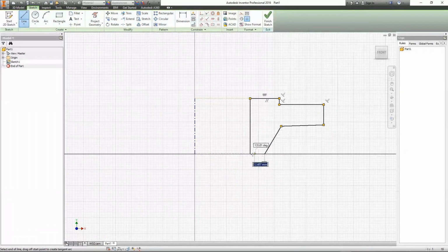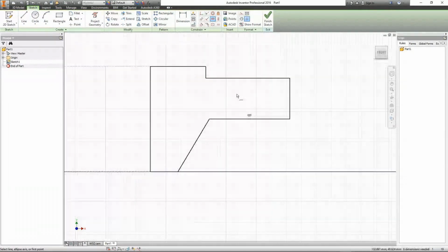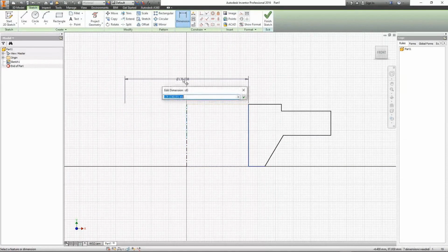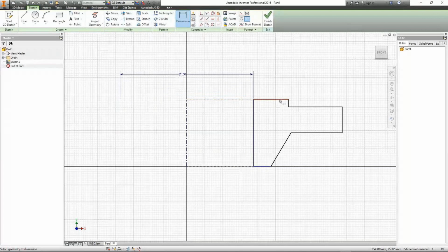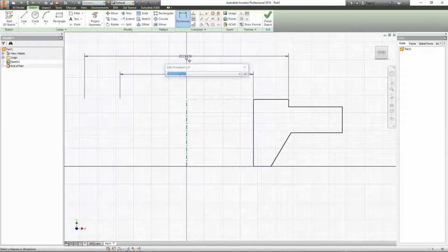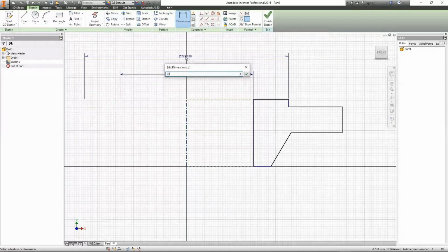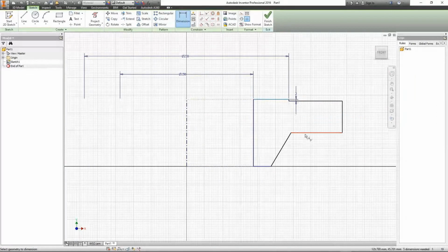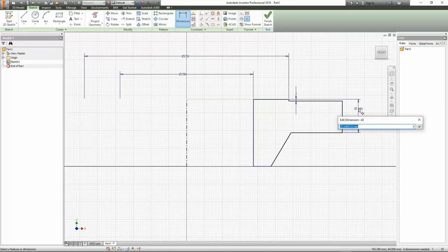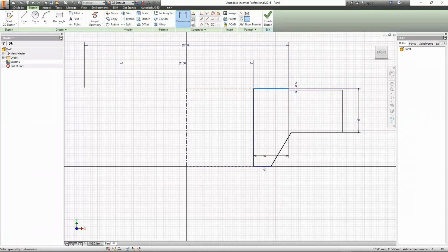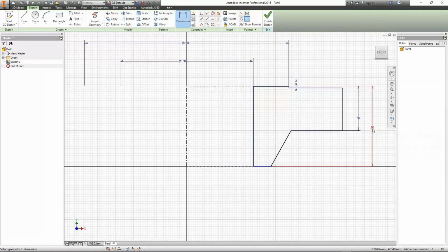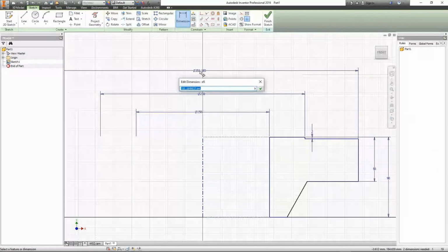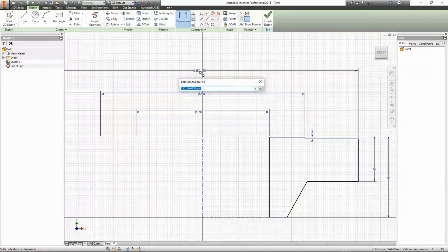Let's make this line a horizontal line like this. Now let's define the dimensions like that. Raised face diameter. Height. The total height. As you can figure, you will need to define each dimension and make each line by hand, like that.